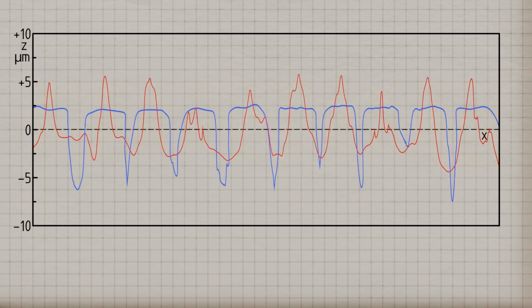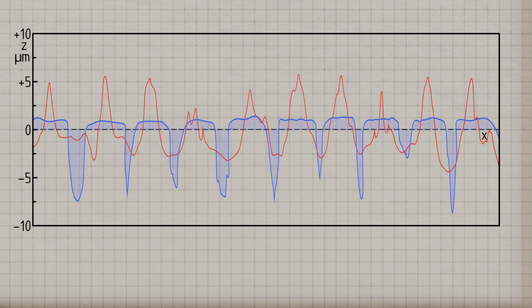Even upon closer examination of the surfaces, it becomes evident that both profiles enclose approximately the same areas with the profile mean line. Therefore, in both cases, we also obtain nearly identical RA values. Despite the nearly equal RZ and RA values, the 2 surfaces exhibit clear differences. This is where the mean peak height comes into play, which allows for a distinction between the 2 roughness profiles.